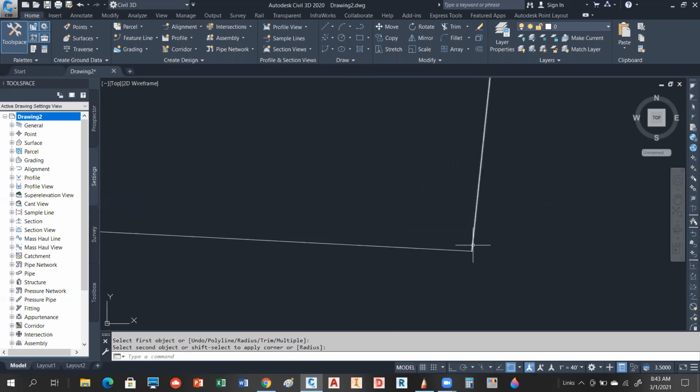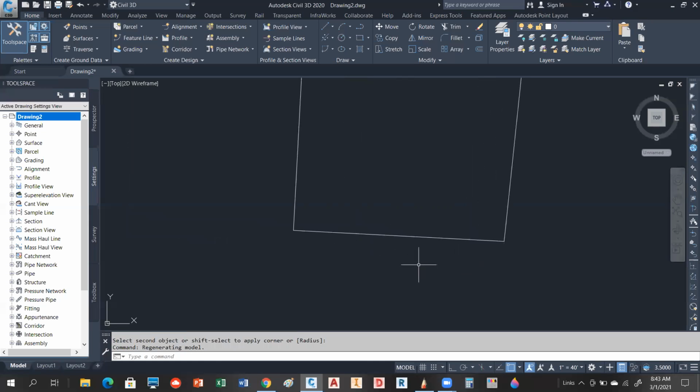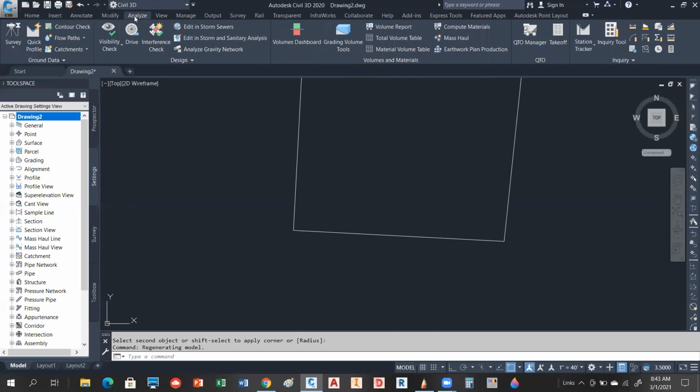Okay, we can go out and look back at our picture now. And if we would do an analyze on these lines, we'll see we probably didn't change anything to 2 decimal places at all. So if I list this line, you'll notice that that line is 484.69, which is what's given on the plat. And the bearing was held, so that didn't change. And right there, we've got that.